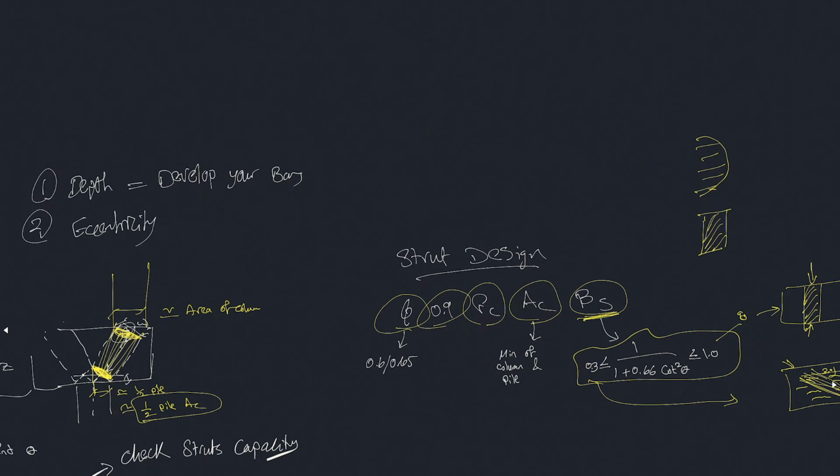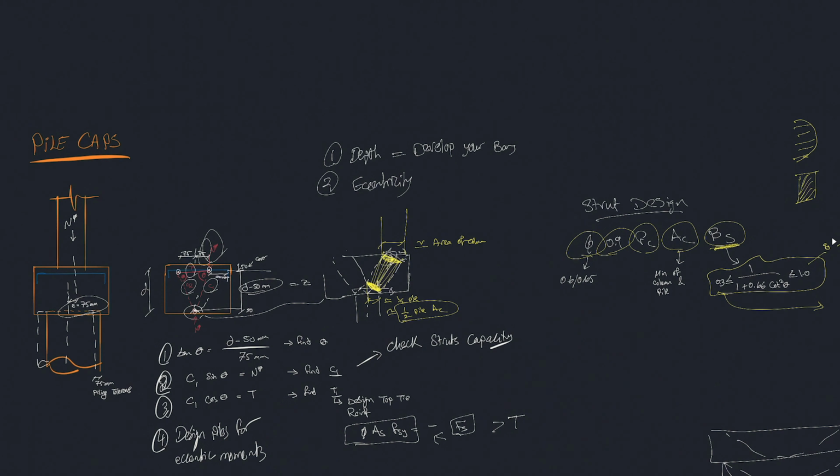So let's recap here for a single pile cap how we designed it. First, we sized the depth based on the sufficient length required to develop the bars through the pile cap. And then we set out our strut and tie models based on minimum eccentricity. We worked out the geometry of that. We knew where the tie was going to be placed and where our struts are.